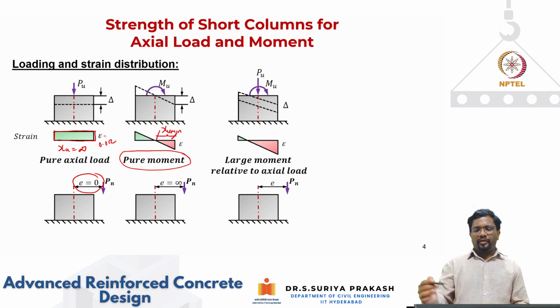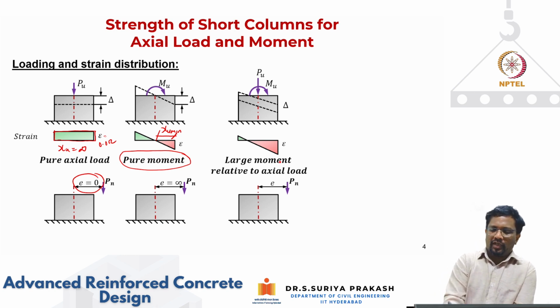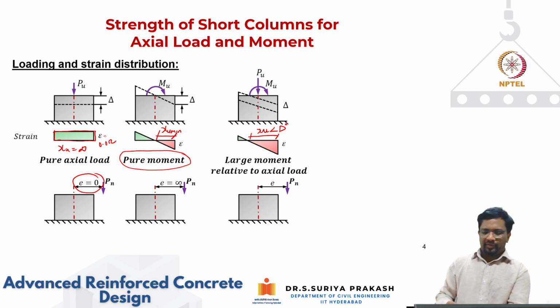So you will have a high bending moment, and as you know, the bending moment is P times e, right? So Mu will become high, and it also has axial compression. When the bending moment is high, most of the time the neutral axis value will be less than the depth of your section, when you have a large bending moment.